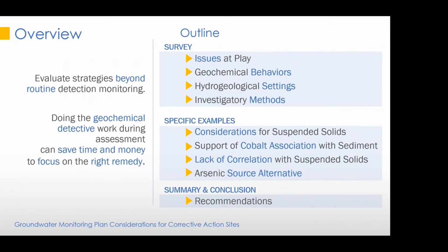The first is a classic interwell model, where you have groundwater background up gradient from the CCR unit. Then it travels underneath the CCR unit. And then in the downgradient side, you have your detection monitoring wells. And the idea is that any difference between the up gradient and the downgradient wells is added from the CCR unit. And so that's the kind of strategy you have.